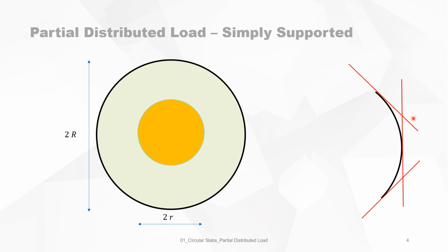So when we have 2 rotation axes on this side, then on the other side of the slab, for instance here and then there, you can now draw a line where the yield line should be, which is perpendicular to the circumference.